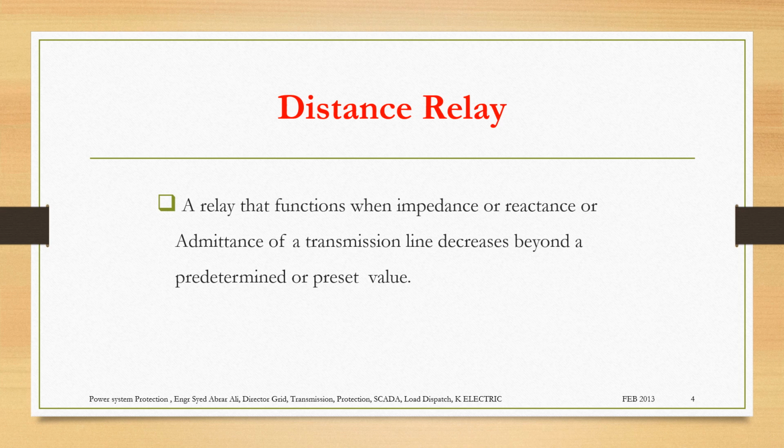So you will be talking about one kind of distance relay. Whenever you are asked what you use for the protection of the transmission line, you can start with the overcurrent earth fault and mainly the distance relay, not the impedance relay. Remember this.